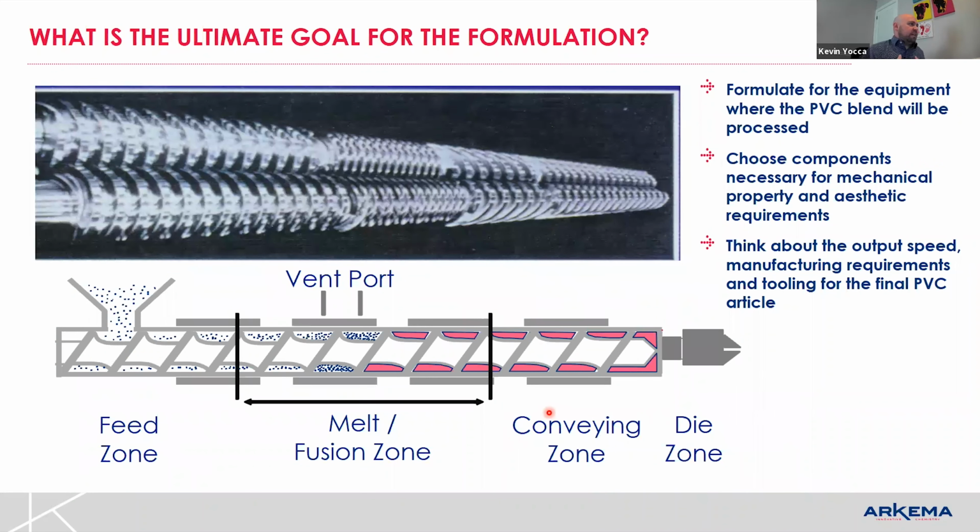What this means to me, if I go back to the gelation and what we looked at with the torque rheometer, is that you're doing the same thing now. And with just your paraffin wax and calcium stearate as an example for lubricants, you can start to take notice in your extruder where you want things to happen. And if we think of, again, the fusion and gelation process and those two different things, where gelation is actually starting the 3D network, but we're compacting the powder, we're starting to get association and aggregation, and then fusion might happen somewhere around our vent port.